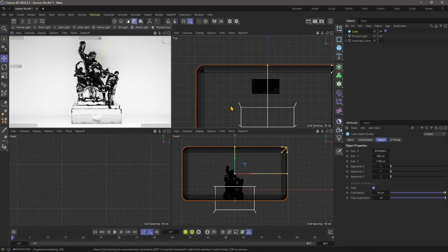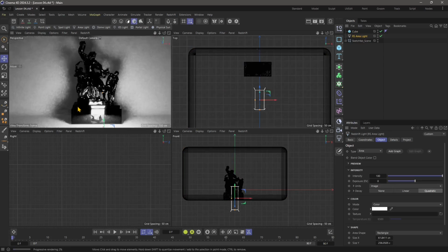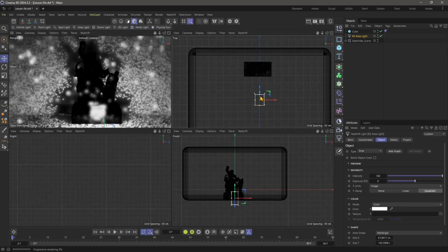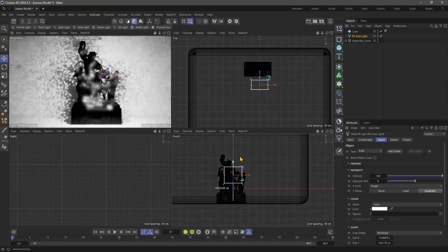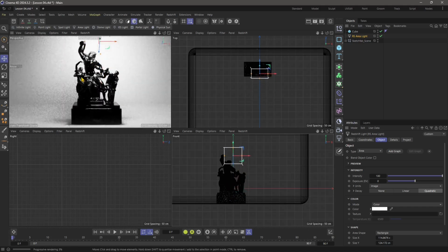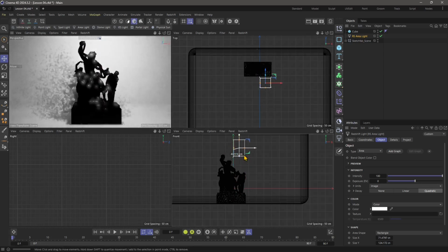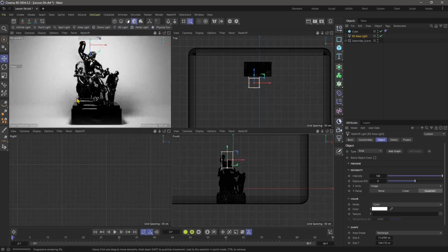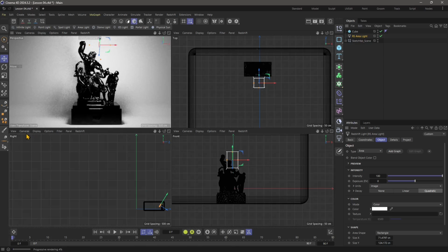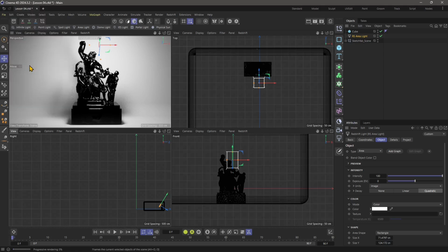Now, of course, one light is usually not enough. You need a system of lights to have a good result. But let's decrease this, and we can see already a little bit better. We can also see the light being reflected on the object, and on the floor. So I'm going to push it up a little bit more, and now it's coming from the top, and it's looking already interesting, but we can fix it even more. So you can position the area light. An area light is not like an infinite light, so it's important where you position it, how you direct it, so how you rotate it, and so on. It's more like the spotlight than the point light.